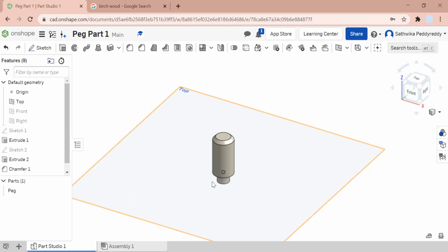And before you go, this is sort of a fun project for people who want to calculate using Onshape. It's really helpful in terms of area and volume calculation. So what you can do is down here, you should be able to see the show measure details. When you click on that, it's going to ask you to select entities to measure. So what you're going to do is you can click on any part and it's going to tell you the area of it. Since I selected this flat 2D surface, it's telling me the area.